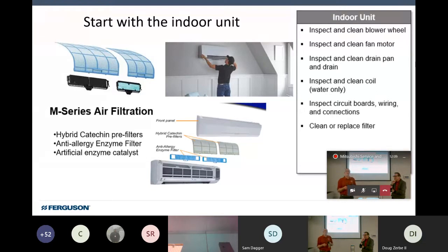The goal here is to prevent the coil from getting dirty, and when it does get dirty, it only needs a light cleaning that oftentimes you get away with water only. Rinse it down. Now, a little bit of cleaner if we need it. I found Simple Green works. Right. So yes, very good. So a light diluted solution of Simple Green could be used on that indoor coil.